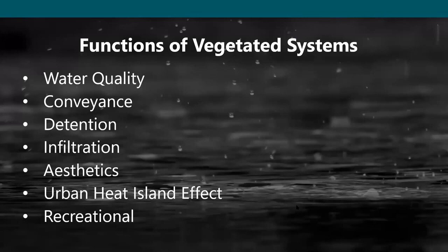And then the question, how do you define bioswale? Generally, when I talk about a bioswale, it's more of a bioretention or a rain garden that helps convey water. So it'll generally be sloped, and it'll allow water to convey from one point, maybe an upstream point, down to either your overflow or where your engineered soil is. So typically when I think of bioswale, I think of just a vegetated system that helps move water.